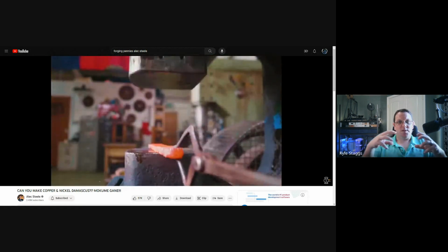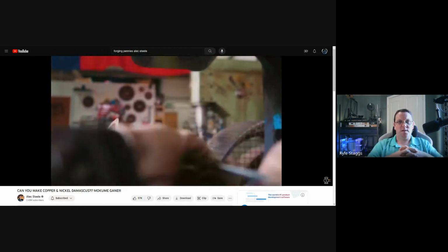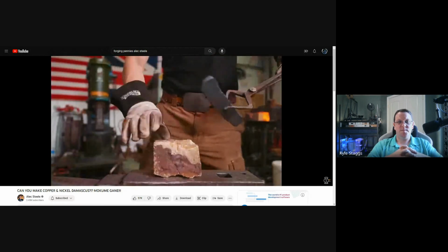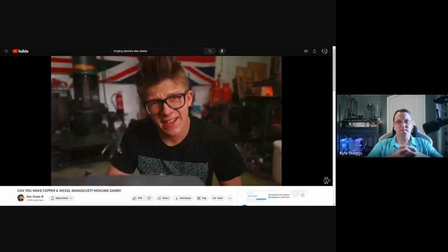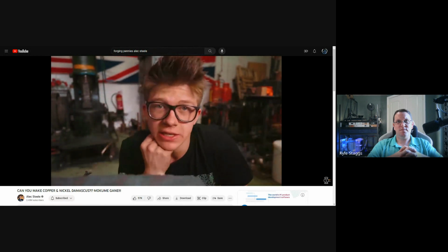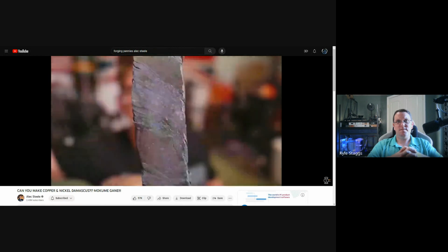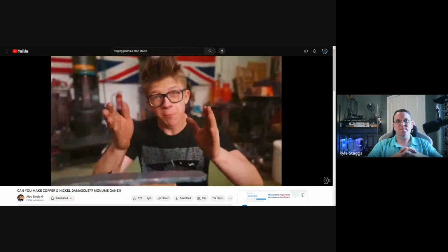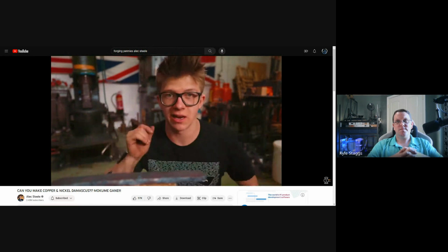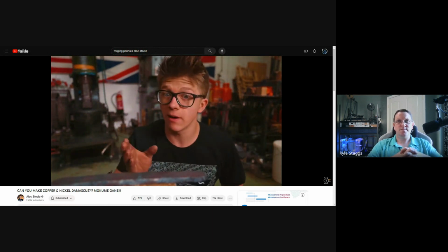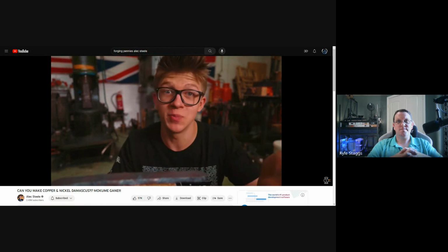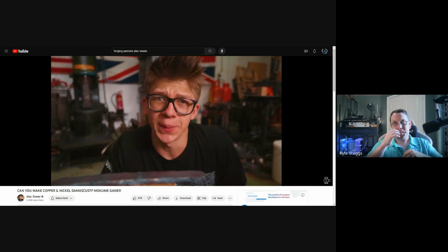At every step, he's having to stretch and elongate those grains to forge these different materials together. So that is attempt number 1 of Mokume-gane. And how do I feel it went? Yeah. Very, very crusty. So I have no idea if we're going to get anything from it. It's possible that it's just the outside layers where they didn't fuse, because of course, once we twist it, all those outside layers are surrounding the periphery of the material. And hopefully that means that once we grind this thing, we can expose solid fused material in the center. That is the hope.